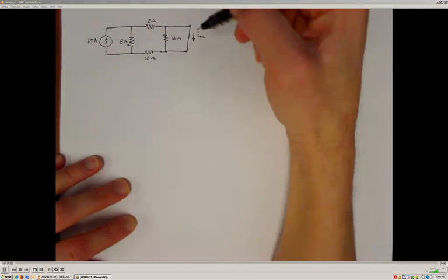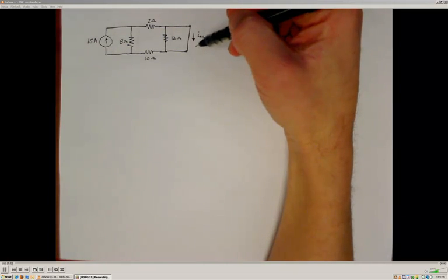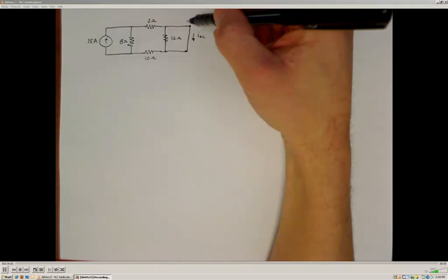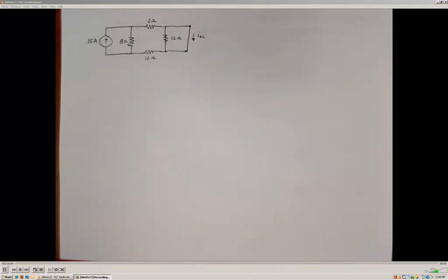we need to move on to determine the short circuit current, as if we connected our two output terminals together directly with a wire. I want to know how much current runs through that wire.